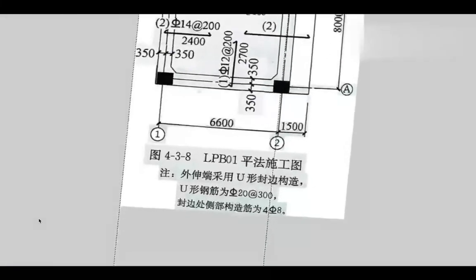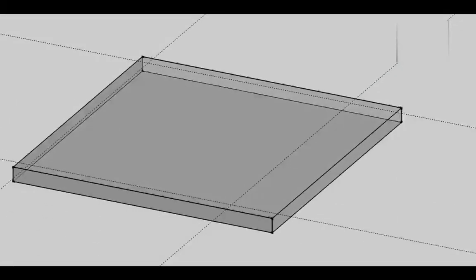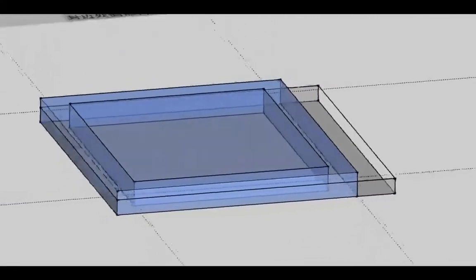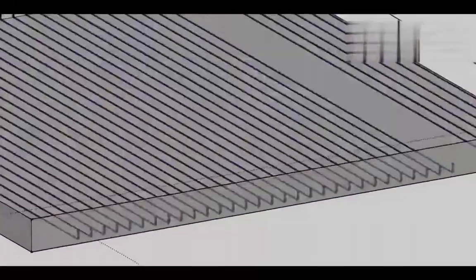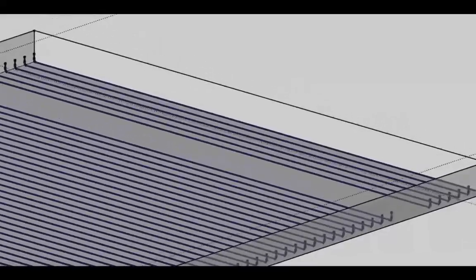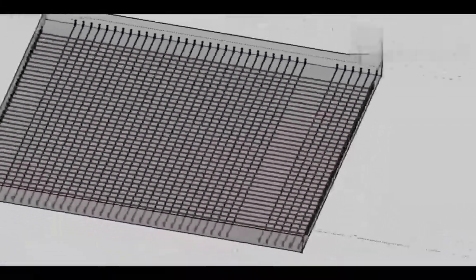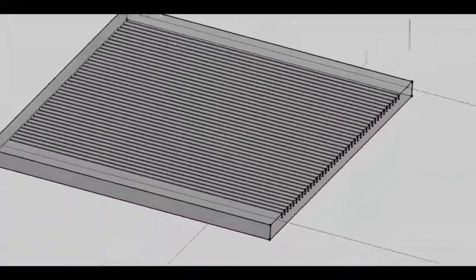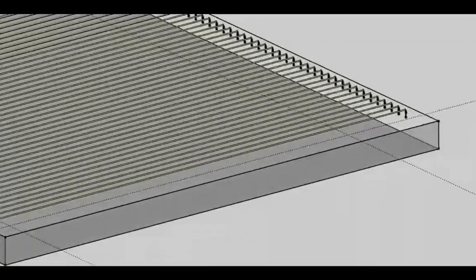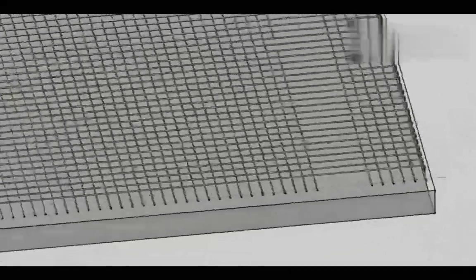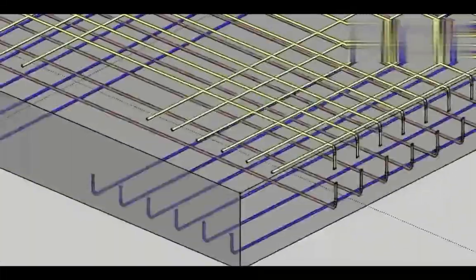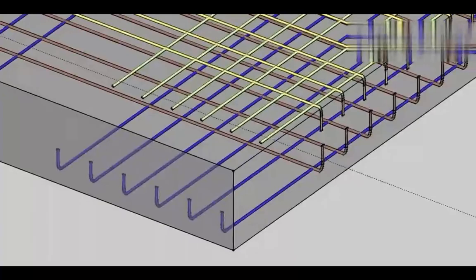The beam slab foundation is adopted, and the design level of the foundation is class A according to the distribution characteristics of the superstructure load. Thick slab foundation is adopted in the towers, and the beam slab foundation is adopted in the podium with relatively small load.